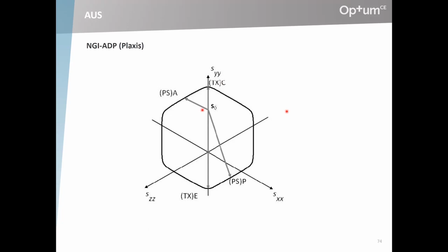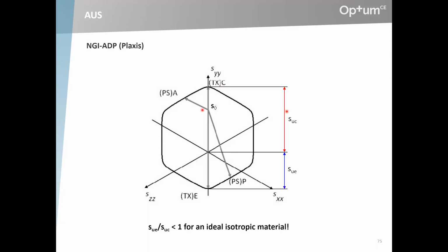That's not what you find. So then anisotropy is introduced by shifting the yield surface along the appropriate axis. So you start from a wrong starting point, and then you correct it by assuming something that is also wrong. To emphasize again, extension to compression ratios less than 1 are a totally expected feature of an isotropic material. It has nothing necessarily to do with anisotropy.